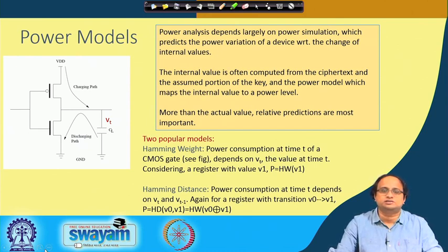But before that, let us discuss the power models, which is a very vital aspect of doing your differential power attacks. A power model typically means it is a simplistic model through which you estimate, or I would say rather guesstimate, the corresponding power consumption.